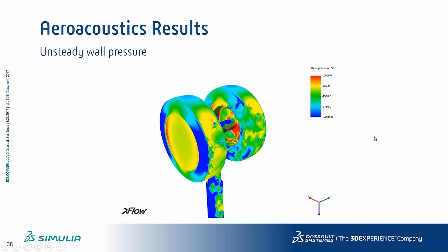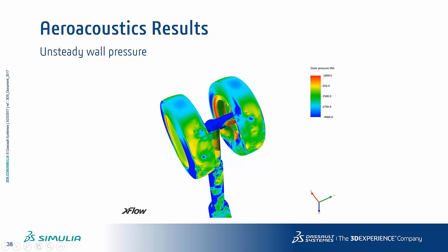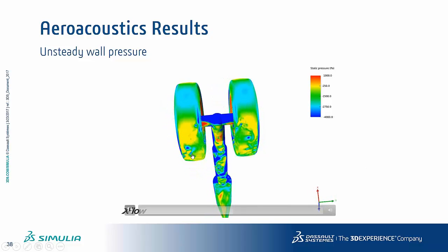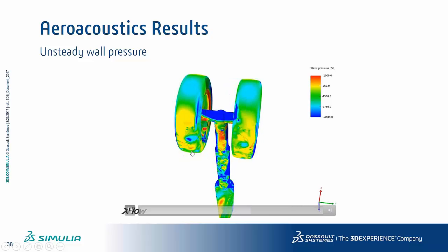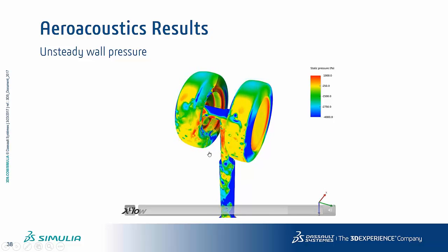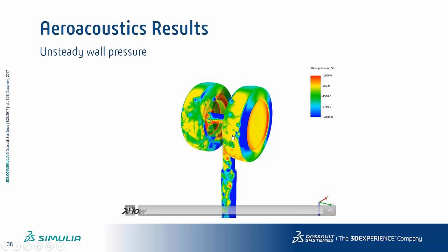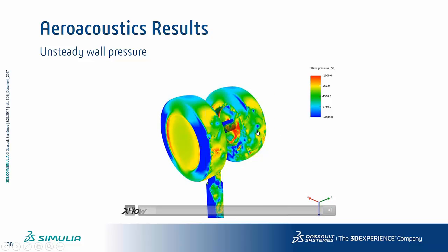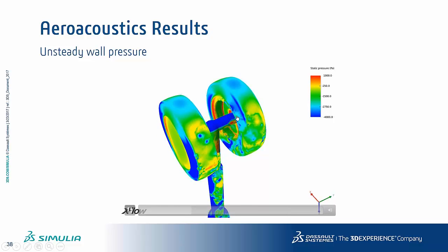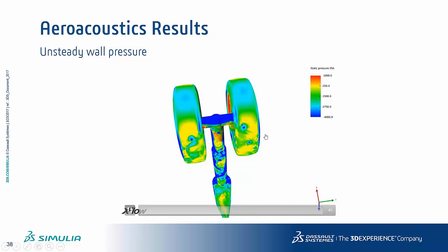So we measured the fluctuation of pressures at different stations. You can see here a video showing the pressure field on the geometry, so you can see the pressure probes that were used for measuring the pressure fluctuation. Unsteady wall pressures are used, and you can see you've got a strong fluctuation in the separated region here. That gives your acoustic fields and the spectrum you want to look at. In this region where separation occurs, you've got some regions where you can see some eddies and recirculations.